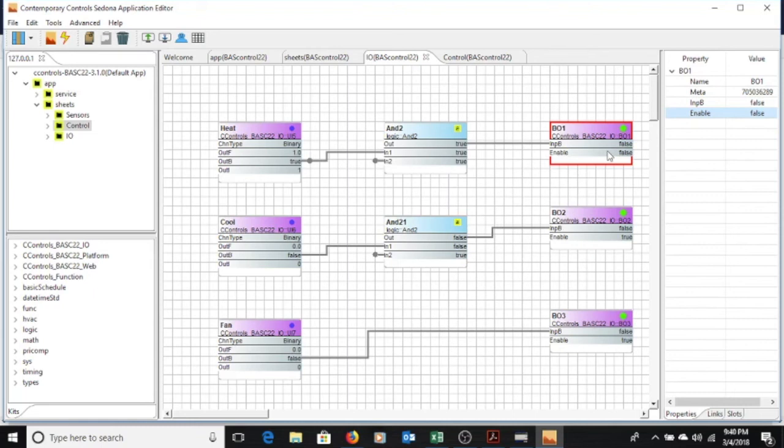Remember that for your lab when a student's about to fire something up and it starts sounding like a motor's screaming for the last bit of its life as it pulls locked rotor amps 25 times in a row. Just remember, keep that in mind. Enabling points is a good function. It's not annoying, it's a good function for commissioning.